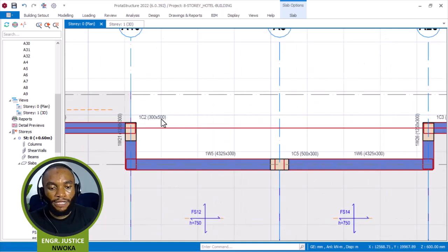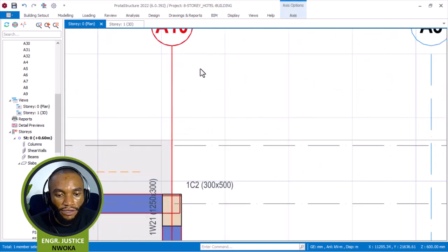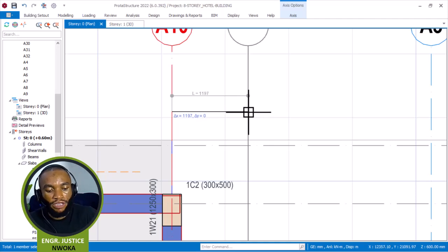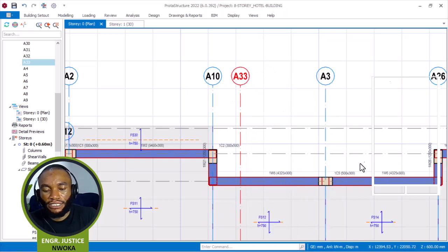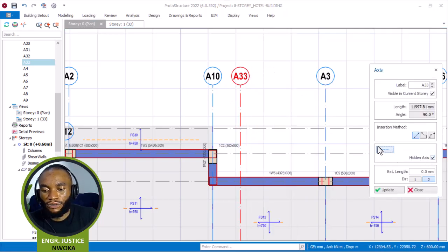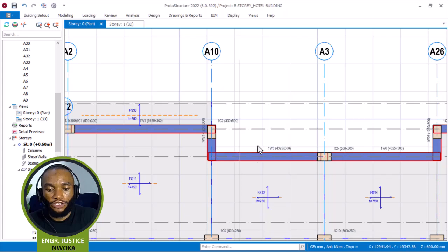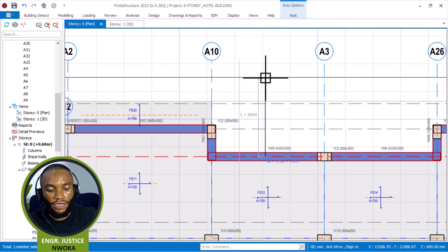Okay, so with this now, I will then move on to this other side. Now, this place, I have to offset again. Offset from here, okay? Right click here, offset by 1 meter, F2, 1000, enter, escape, right click, properties, hidden axis, which is ghost axis, okay, that's fine. And again, come now, here too, offset this also, right click here, offset, come here, F2, 1 meter, correct, enter.